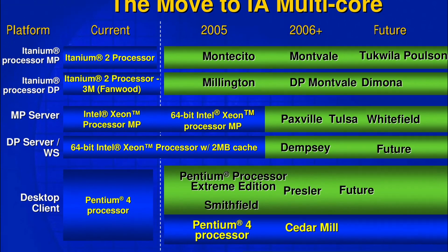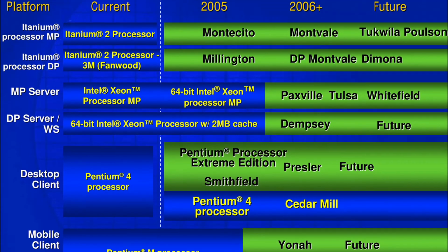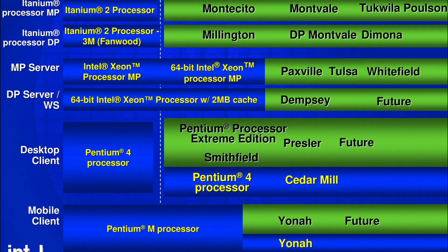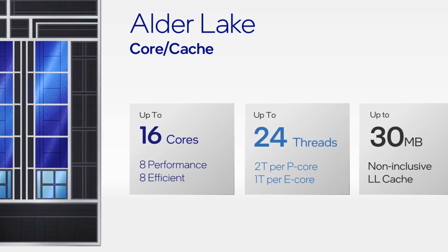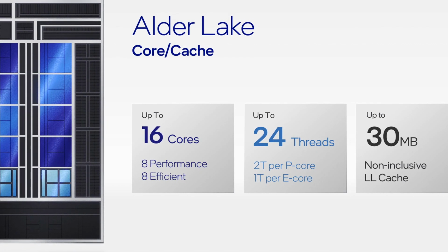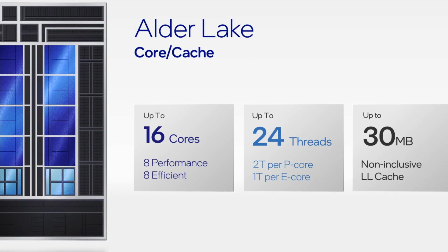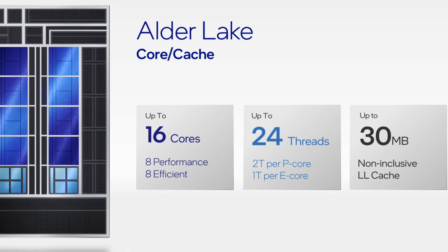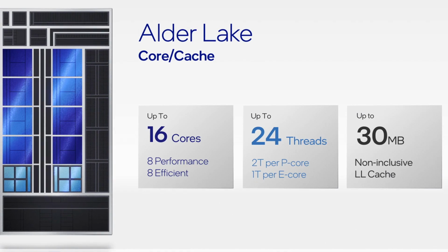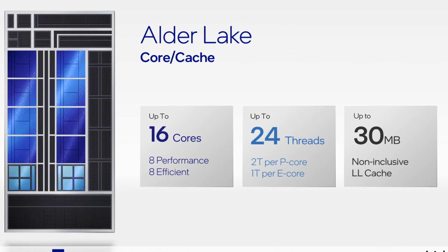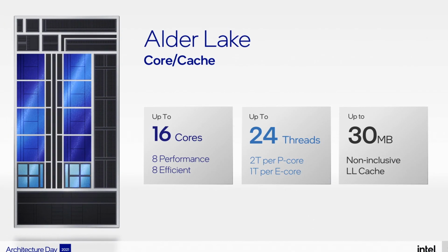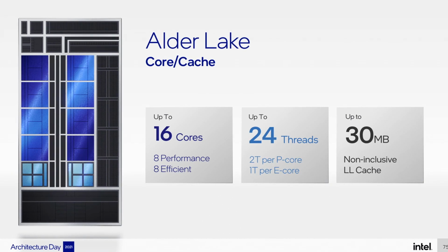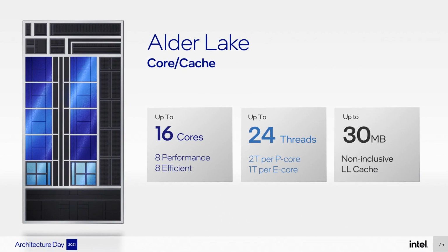Of course, back in the day when we only had one or two cores, the quality difference between the cores was relatively small. So there was not that much benefit to maxing out each core independently. Nowadays, even mainstream CPUs have up to 16 cores. That means the quality difference between the cores can vary greatly. In addition, the heat produced by 16 cores at full load will be much higher than the heat produced by just a couple of cores at a light load. So if you tune your system for the worst case scenario, you will miss out on a lot of performance in the most common scenarios.